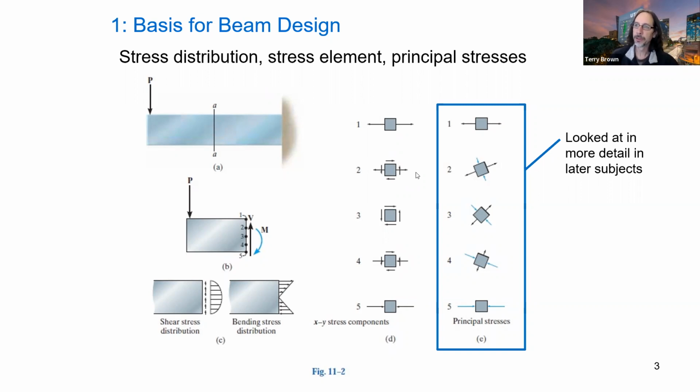We've got a normal stress component and a shear stress component, and then we get the principal stresses at a particular orientation. So that is equivalent to, here's my actual force, the paddle pop stick, and my coordinate system is aligned along the line of the resultant force. Okay, so that's the analogy we're looking at here.